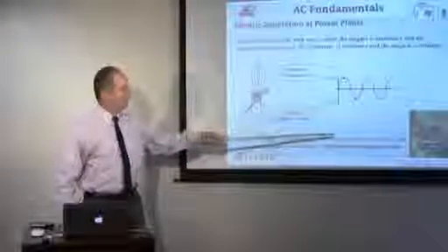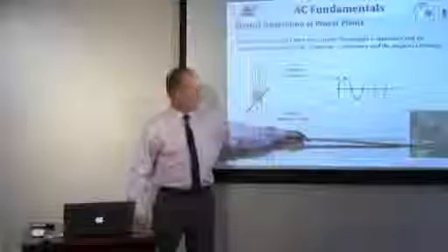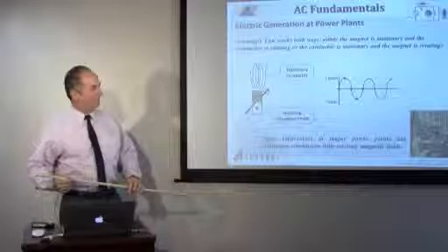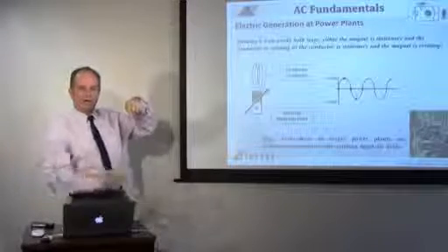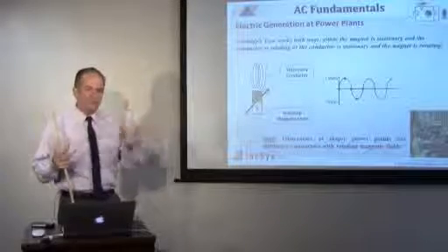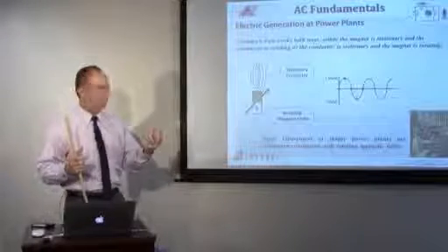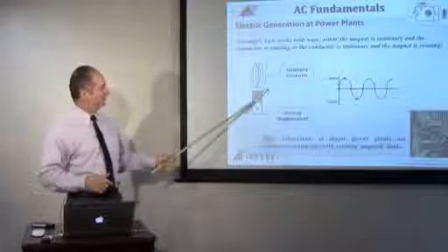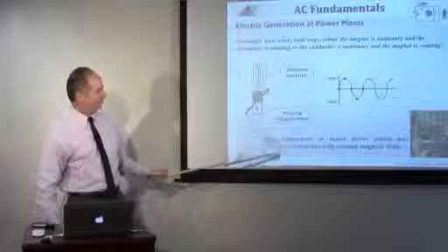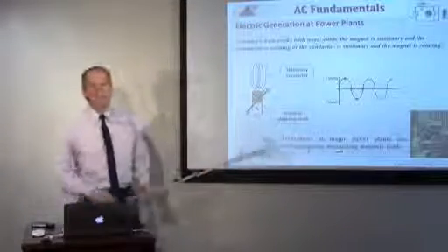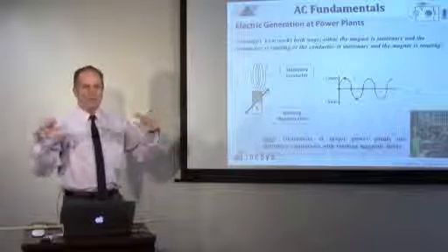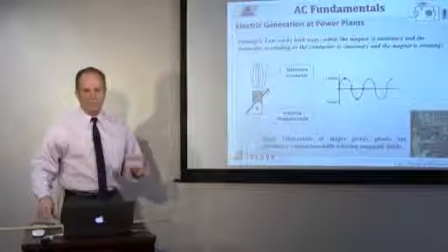So what we have in this picture is a generator that is vertical, and the shaft is rotating because of the water flowing down below. It's rotating the shaft. We have coils on the outside, and the center rotating shaft has the magnet. And the magnet is spinning, causing voltage to be produced. Generators at major power plants use stationary conductors with rotating magnetic fields. Okay? And if we were to take that generator and put it on its side, it'd be like a regular power plant generator. We'll get into that too.